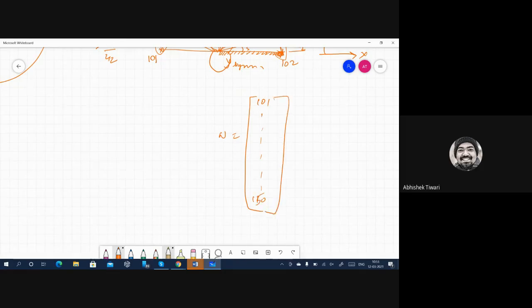These are the nodes where you have to apply U1 and U2. So write a for loop that for node number 101, apply U1 equal to this, U2 equal to this, and so on. Keep on repeating, change the value of n, and the boundary condition is applied. Once you have written that code, run that script in Abaqus so that the boundary condition is applied, then run the job. This is how it should be done. We will see on Monday, okay?